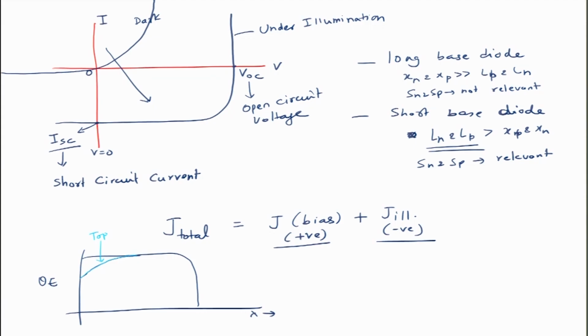and if your quantum efficiency is decreasing on the higher wavelength side, then you know that you have a decrease mainly from the bottom part of the solar cell. If you have a decrease in the middle, it comes from somewhere in the middle where you have recombination taking place or some other effects. This will be helpful for you to look at your data yourself if you work on solar cells, and analyze which of the layers may be playing an important role, especially in the context of bilayer junctions like PN junctions, wherever you have silicon solar cells.